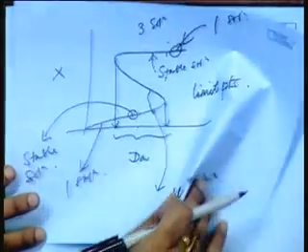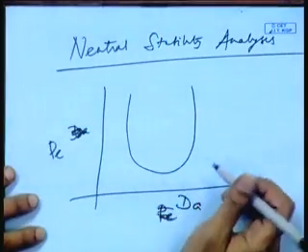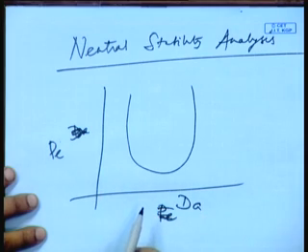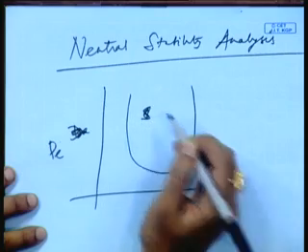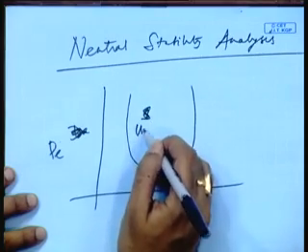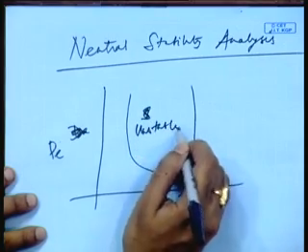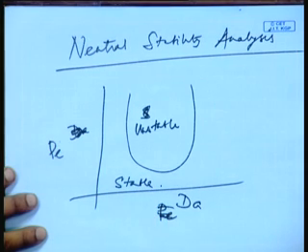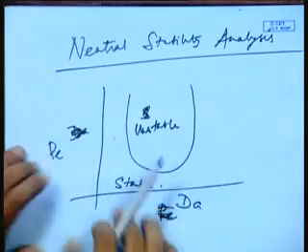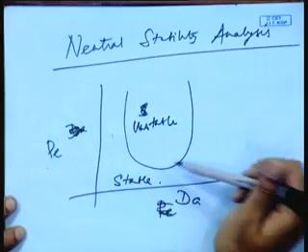So, what you need to do is isolate or figure out, in the parametric plane of Peclet versus Damkohler, whether the system is going to be stable or unstable. So, this is a branch part where it's going to be unstable and the system is stable here, which means that you choose your parameters such that it stays within this range. Okay, it stays within this stable part.